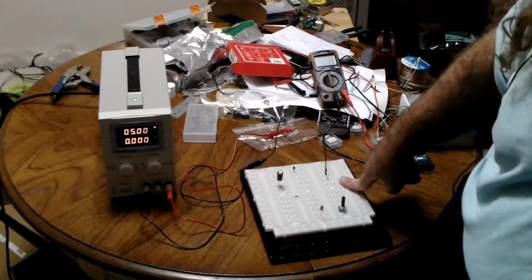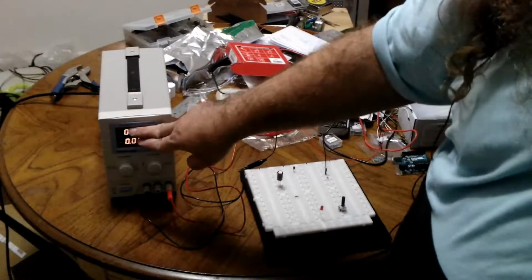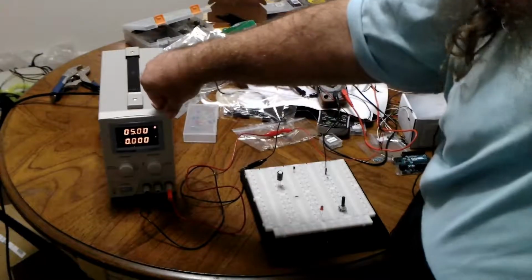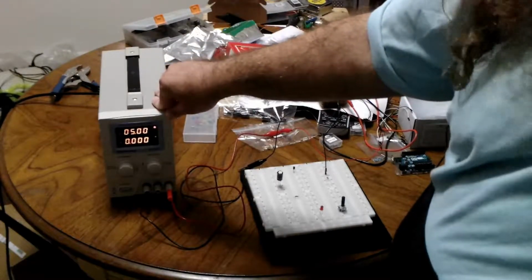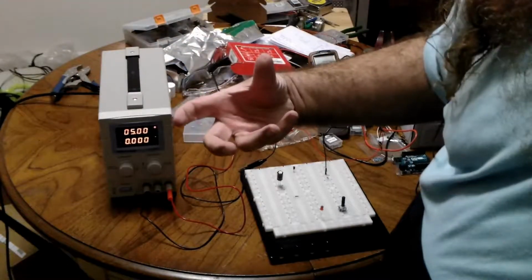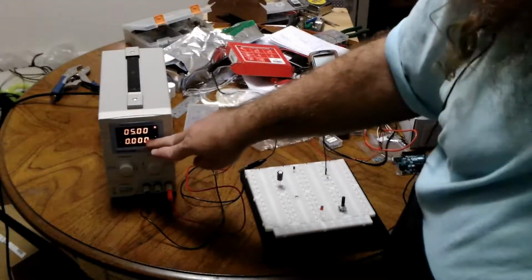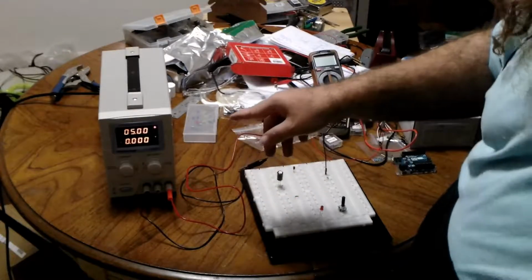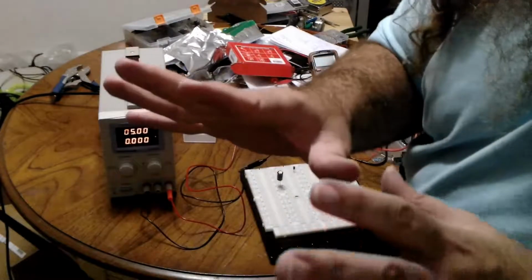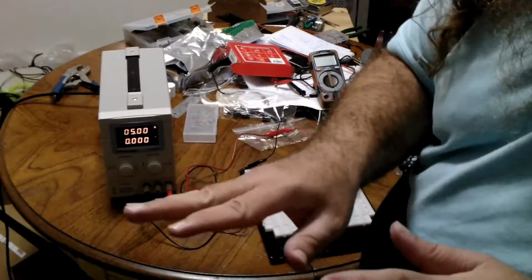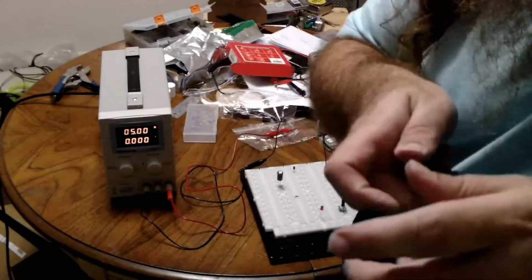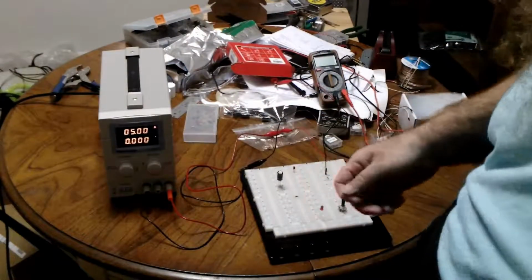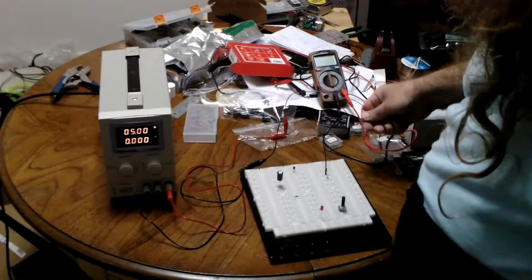But then the capacitor is going to charge to whatever voltage that is and stop drawing current. So then this thing is going to say, oh, it's not drawing 1 milliamp. Let's turn the voltage up. And then the capacitor will start charging, drawing way more current, and it'll say, oh, wait. But then it'll charge to that voltage and stop drawing current again. So the capacitor is kind of like, okay, I'm good. And the power supply is like, here you go, wait, okay. They're kind of fighting each other until they charge. So let's watch it happen.